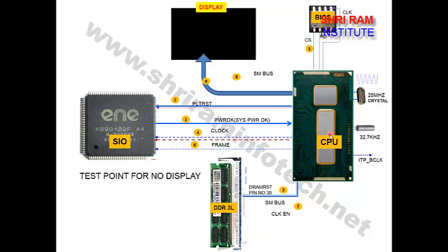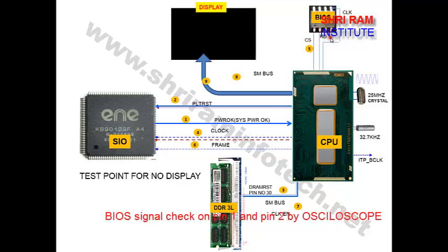Okay, so you have to check the CPU like that. So you have to check the clock at the LPC port. The next step, after the clock, is that the CPU accesses the BIOS. BIOS is an 8-pin chip.